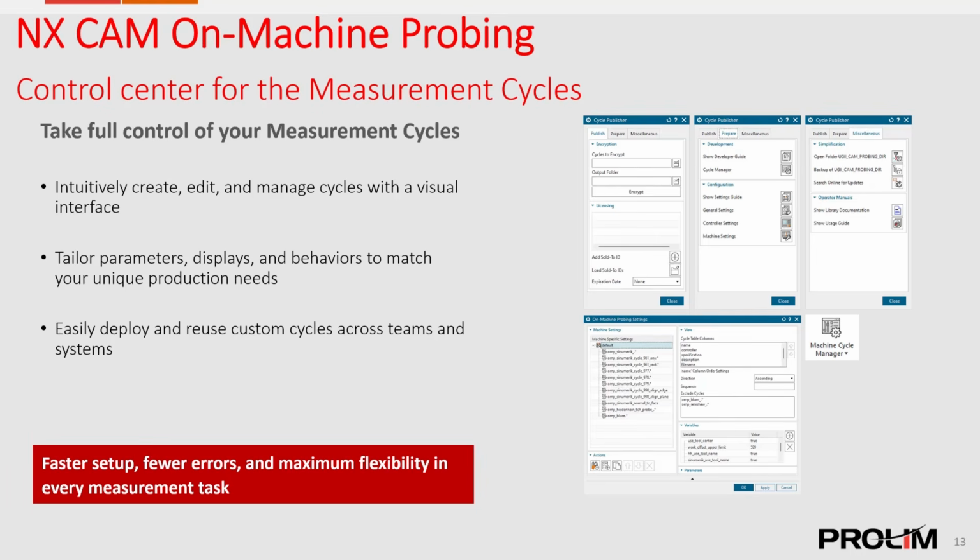Let's take a first look at NX CAM on-machine probing. It's a powerful innovation in the measurement process. The Machine Cycle Manager: you can now use the center for managing measurement cycles. This tool brings a highly visual and user-friendly approach to managing measurement workflows. You can now perform a wide range of steps graphically, which significantly reduces the setup time and simplifies even complex operations. One standard feature is the ability to create and publish your own custom cycles.